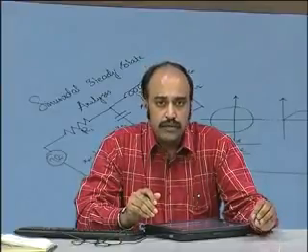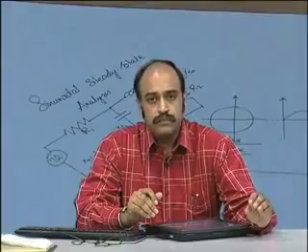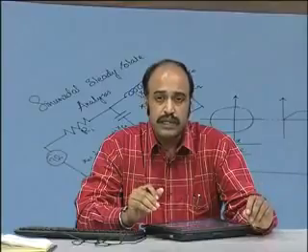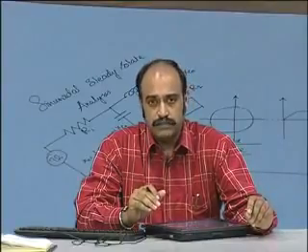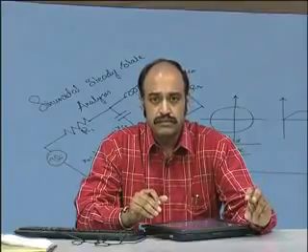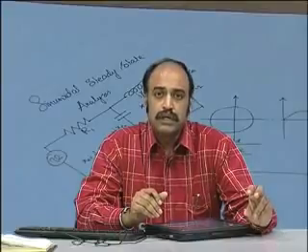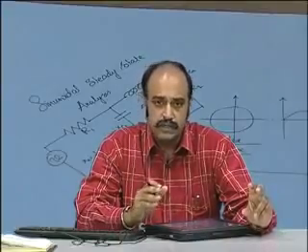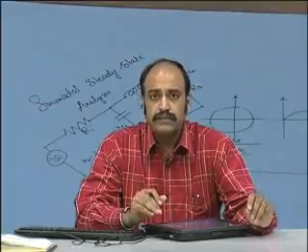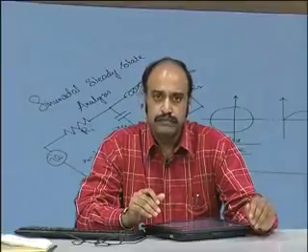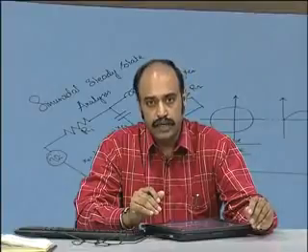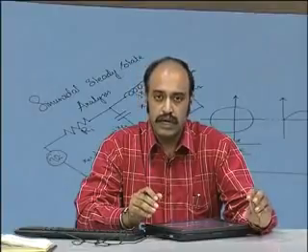The other domain was the frequency domain, where you view the magnitude plot and the phase plot with respect to frequency. That is, at various frequencies, what will be the gain of the circuit, input to output, and what is the phase relationship of the output with respect to input. Now, these at various frequencies are noted down and plotted, and we use the Bode plot in MATLAB to check this out.